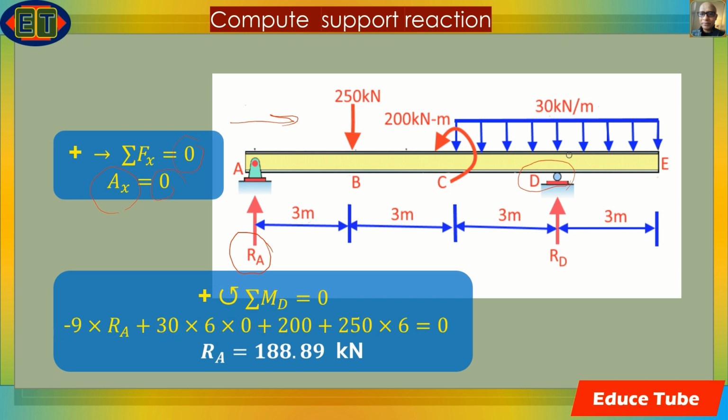Then 30 into 6 into 0, because this uniformly distributed load's center is exactly on the support, so it will be 0. Then the 200 concentrated moment, which is also anti-clockwise, already considered positive, and 250 multiplied by 6, because from D it is 6 meters distance, equal to 0. So Ra we got 188.89 kilonewtons.